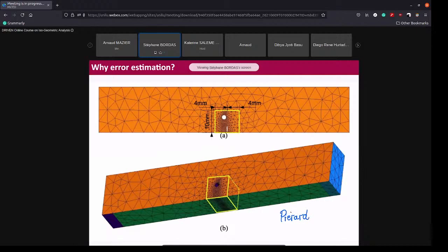So this is a beam. It's got a notch, a pre-crack at the top here. And it's got a hole here. The hole is going to act as an attractor of the crack, because the crack is going to tend to want to go to the hole, because that's what cracks do. They try to reach free surfaces. So that surface here is going to make it easier for the crack to propagate. Therefore, it's going to propagate in mode 1, because that's what it likes best. That's the easiest thing for it to do, propagate in mode 1. So it's going to curve, try to reach mode 1, and eventually hit this hole. So this is what you see.